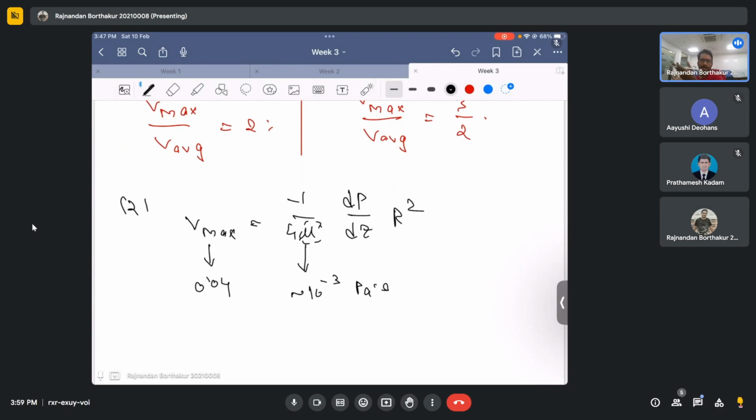Look into this value in the net: what is the dynamic viscosity, because it's a physical property, right? So just see what the dynamic viscosity of water is at 27 degrees Celsius. And this is precisely the reason why temperature is given, simply because the viscosity of fluids typically changes with temperature.